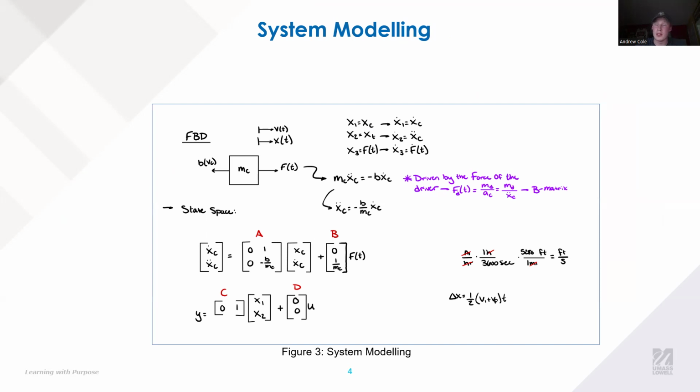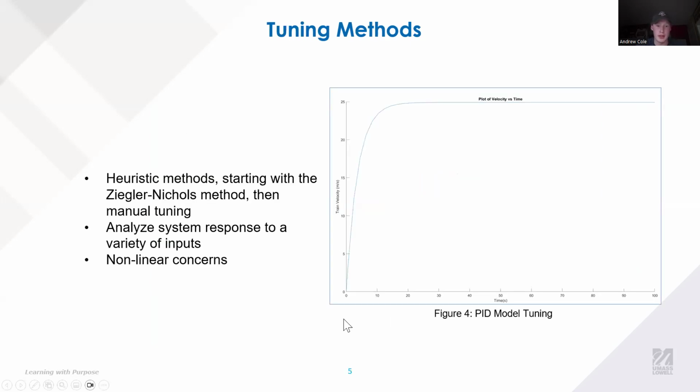And going in the opposite direction was the force of friction between the wheels, and I said steel for the material of the track. So using this, I was able to derive an equation of motion for the train. And using that, I was able to derive a state space model to represent the system. Using that state space model, I was able to derive a transfer function, which was later used when modeling the system in Simulink.